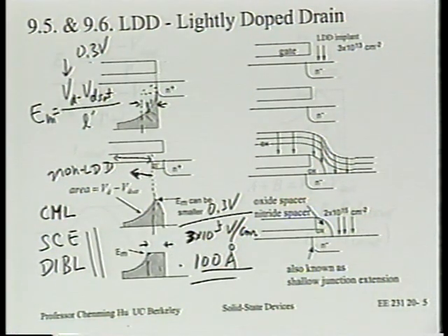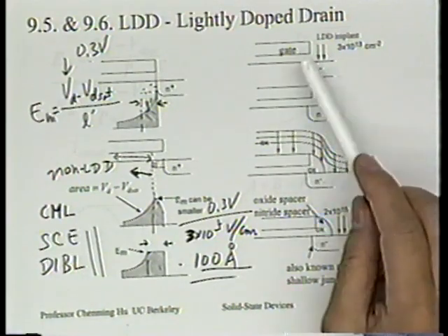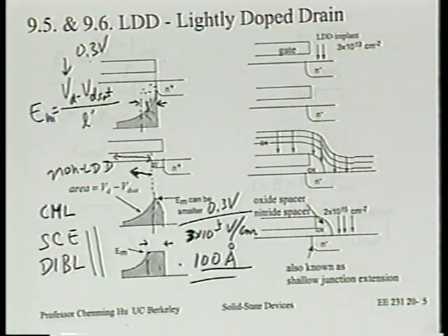And it turns out the answer is a linear function of doping, right? Is it easy to engineer a linear doping concentration profile? It's not easy. Is it too difficult to do something approximate to that? It's not that difficult either. So certainly there are things we can do, all right? It's a little bit like information theory, in that it's always good to know the maximum achievable quantity, and then we can work toward that.